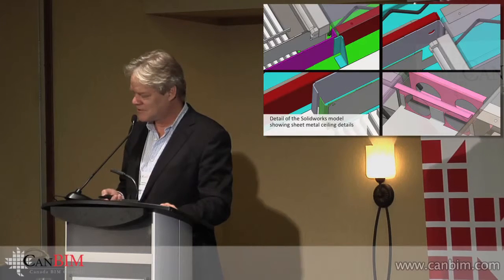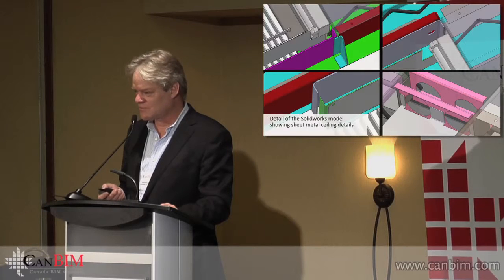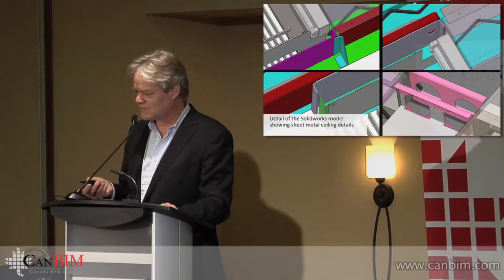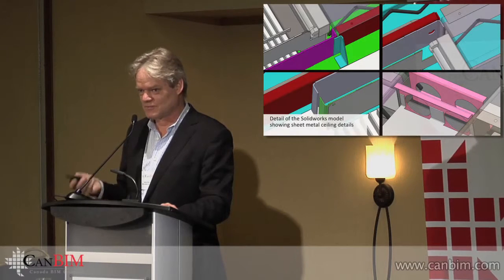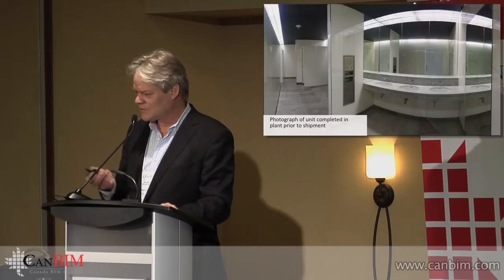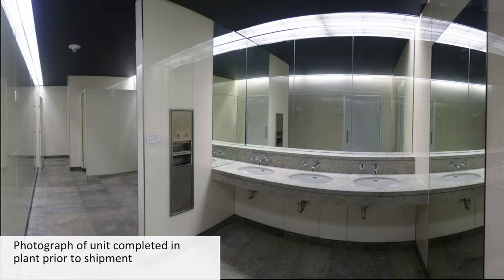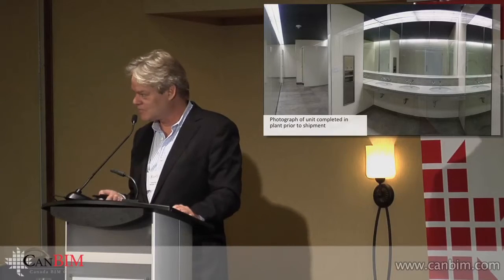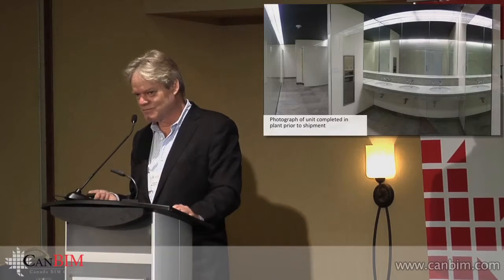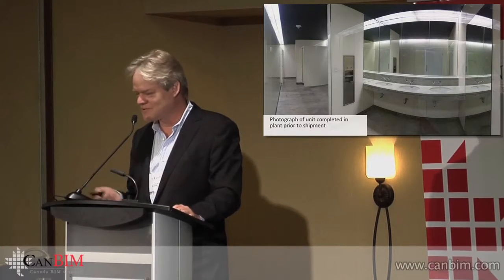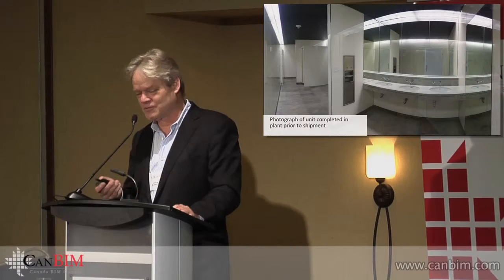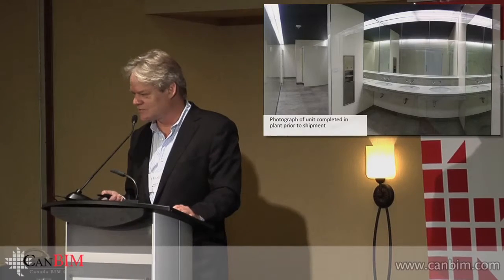to this, that, and the other, you literally add a zero to that. So we were able to make these ceiling assemblies for 1/10 the cost out of sheet metal that it would have cost to make them all out of discrete components in multiple trades shops. So this is a photograph of one of the units that we fabricated, photographed in our plant before it shipped. Sprinklers tested, the tubes in the sockets, the plumbing pressure tested, even the drains pressure tested.